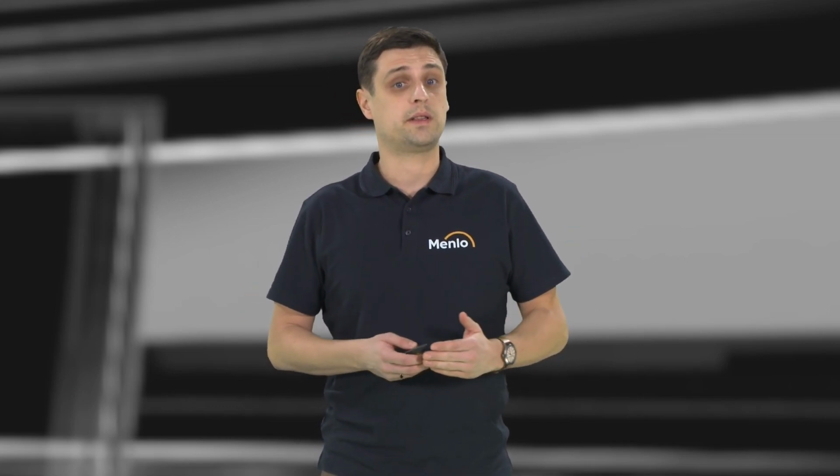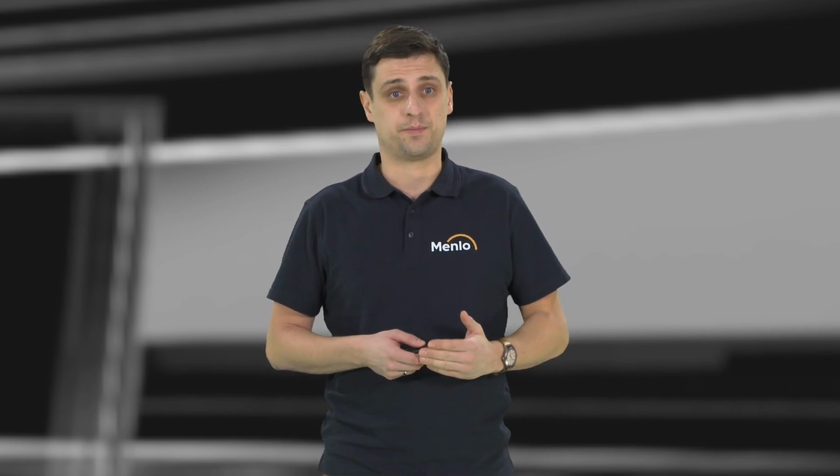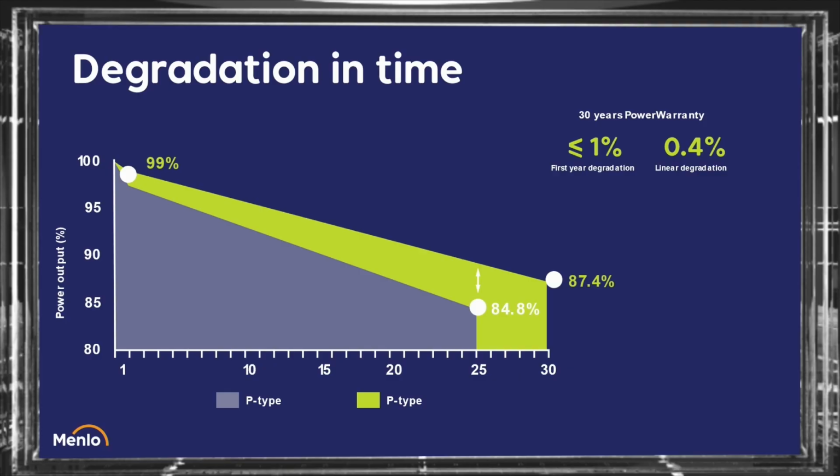So we said that TopCon is better in every parameter than P-type. So what are the real differences? First of them is degradation in time. P-types lose more or less 2% in the first year and about 0.5% every next year.